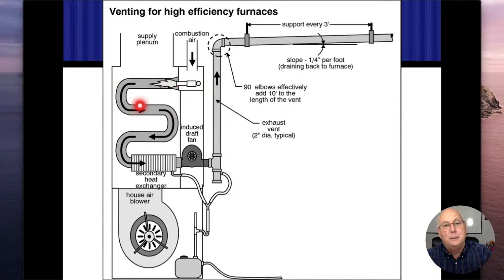As the heat that's been created goes down into the primary and into the secondary heat exchanger, during this whole process, I'm absorbing 95% of this heat that I'm creating. 95% of that heat is going through the house. Only 5% of that heat is being exhausted. I still have 100% of all the combustion byproducts. So I still have whatever carbon monoxide is being produced, whatever carbon dioxide, however much oxygen is left. That's all still in the bad gases, and that does need to be exhausted to the outside.